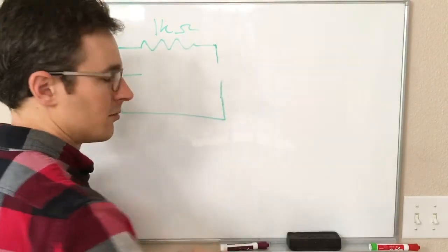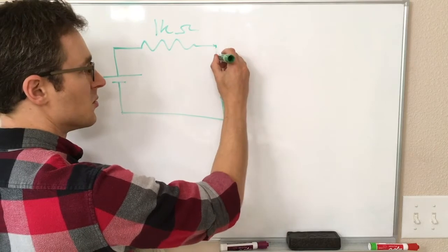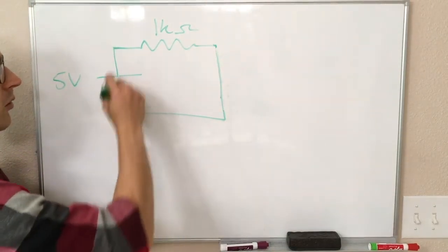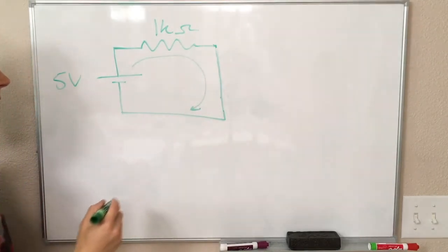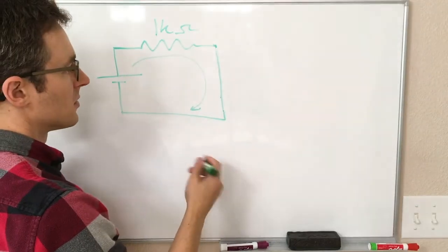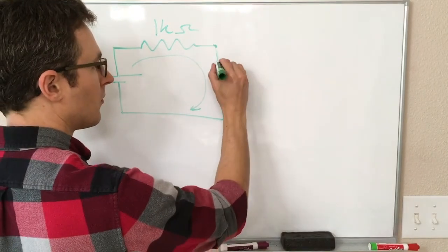So in that way, it does not make sense for our diode to be off. And let's check the other alternative thing we can check, the current method. So here we assume the diode is on, replace it with a wire, and say, okay, well, we have current flowing through it this way then, right? Current going through our resistor back to there. And does that make sense then with our diode picture?